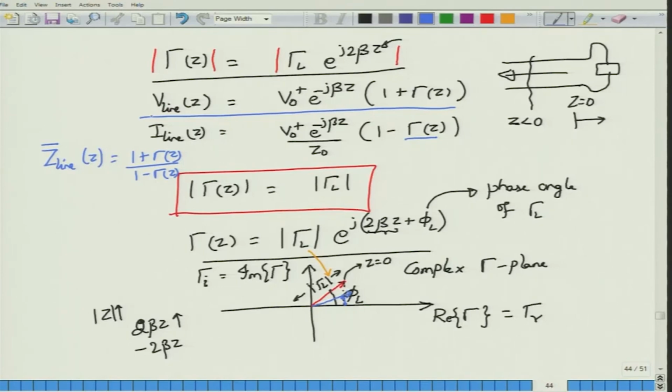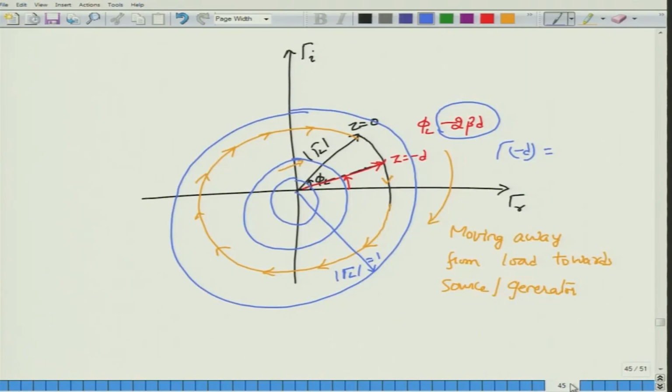This would be the line impedance, and that line impedance will be divided by Z naught in order to normalize the line impedance. Okay. So if you know gamma of Z at any point on the transmission line, you can now know how to do that one by following this particular arc, and you can figure out what would be the line impedance. However, this process is still a little bit tedious because it involves a formula. So what P.H. Smith came up with was a very interesting scenario.